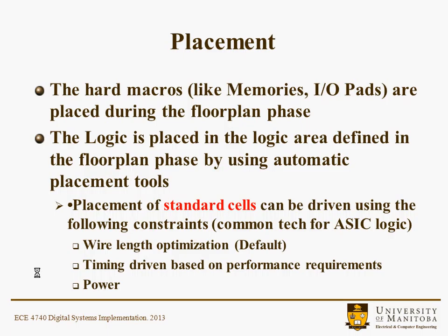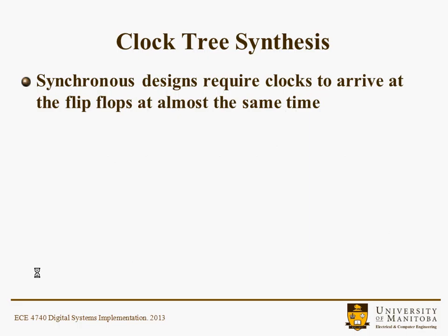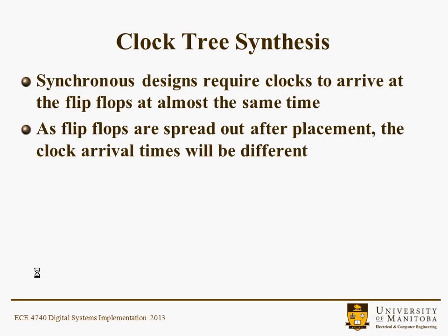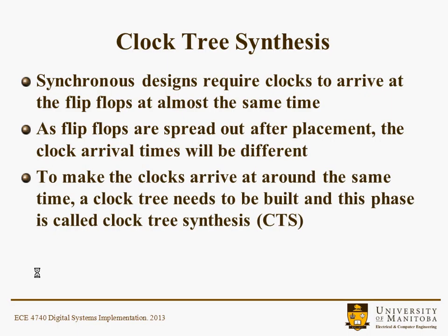Clock tree synthesis is a very important part of ASIC design. It's very difficult because what you'd like to do in a synchronous design is have all the clocks arrive at flip-flops at almost the same time, but the flip-flops are spread out all over the chip after placement, and the clock arrival times can be quite different. So to make the clocks arrive at around the same time, a clock tree needs to be built, and this phase is called clock tree synthesis. We'll look a little bit more into that later, with some examples of it. Certainly some very nice types of clock trees are synthesized, and it certainly gives you a lot to think about when you're building an ASIC.